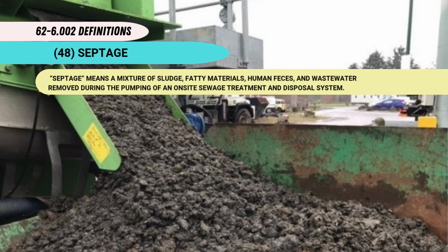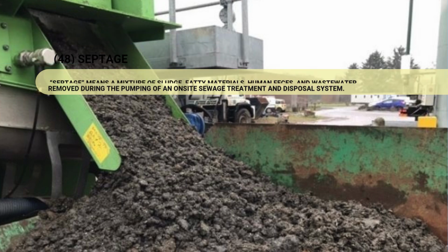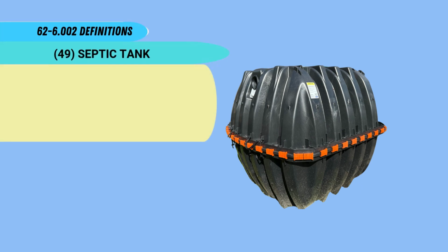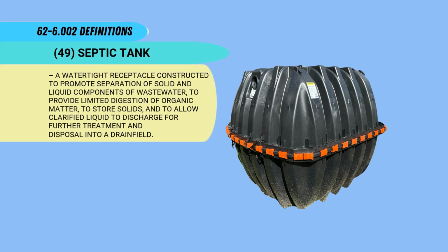48. Septage means a mixture of sludge, fatty materials, human feces, and wastewater removed during the pumping of an on-site sewage treatment and disposal system. 49. Septic tank, a watertight receptacle constructed to promote separation of solid and liquid components of wastewater, to provide limited digestion of organic matter, to store solids, and to allow clarified liquid to discharge for further treatment and disposal into